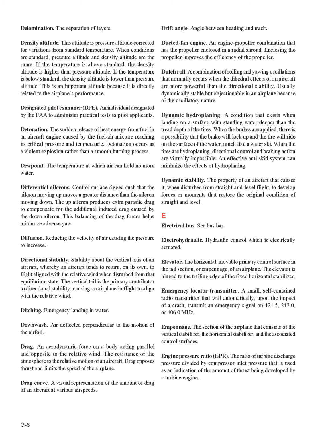Downwash. Air deflected perpendicular to the motion of the airfoil. Drag. An aerodynamic force on a body acting parallel and opposite to the relative wind. The resistance of the atmosphere to the relative motion of an aircraft. Drag opposes thrust and limits the speed of the airplane. Drag curve. A visual representation of the amount of drag of an aircraft at various airspeeds.